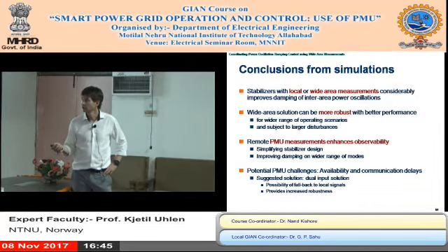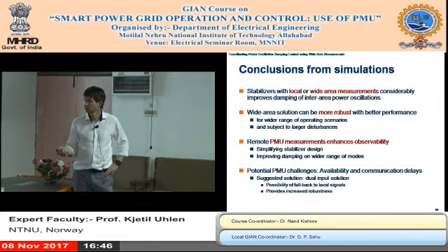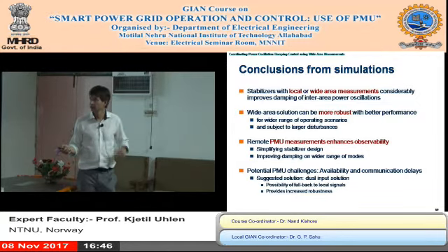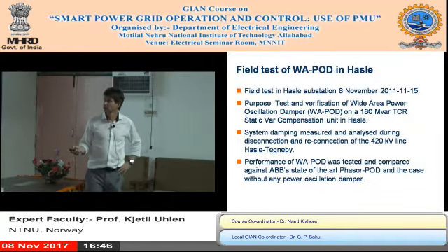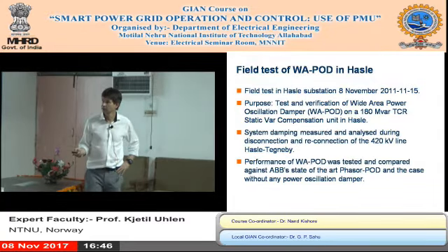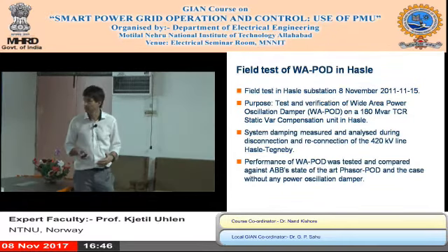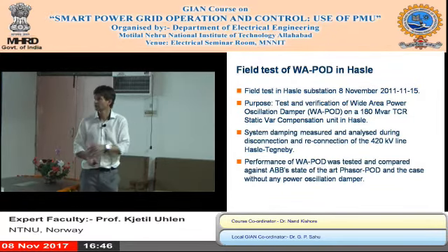So some years ago we did a field test on that at the substation. We tested the wide area power oscillation damper that we had designed on a 180 megavar thyristor controlled reactor. So it's an SVC unit, but only with thyristor controlled reactors combined with capacitor bank, so it worked as an SVC.